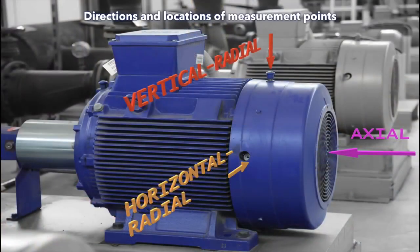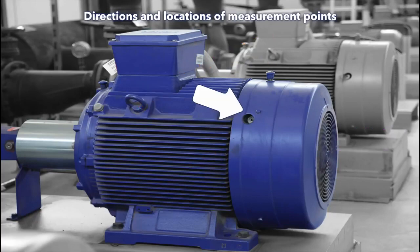The direction of the measurement point, this means radial and axial according to shaft rotation, is important as well. In an ideal world, you would measure in a vertical radial direction and a horizontal radial direction on each part of the machine. But then you will spend twice as much time on each machine to collect the data. Let's make a compromise. Place the measurement point or sensor at 45 degrees, if possible, in a radial position. You will still have information about both vertical and horizontal directions, and you will spend less time on the machine.